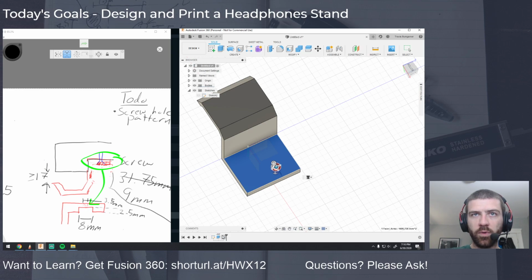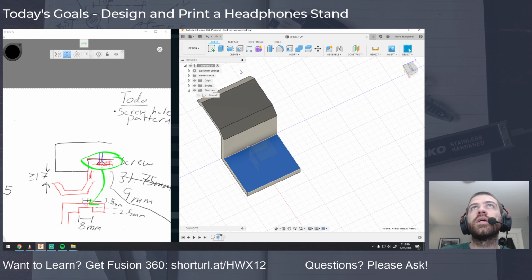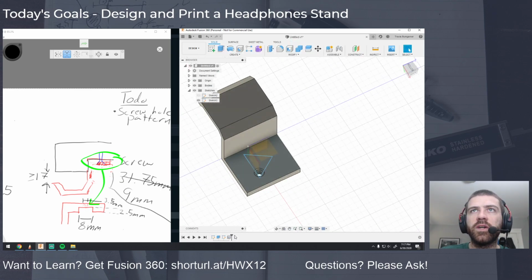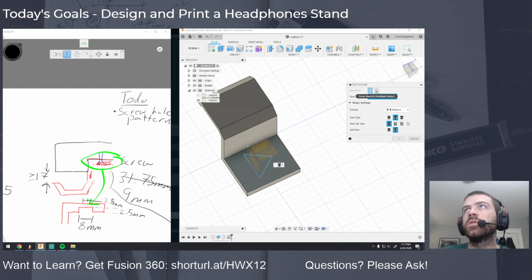So if I go back here and roll back, or step back one, oops. Okay, now I can step back one. The hole's gone, and I can come here and sketch. I believe if I put points on this surface, I'm not going to get too involved in the math first. I just want to see if I can even do this. So that's there, and I go forward, and I edit this feature, and I select multiple. How do I reference the sketch?